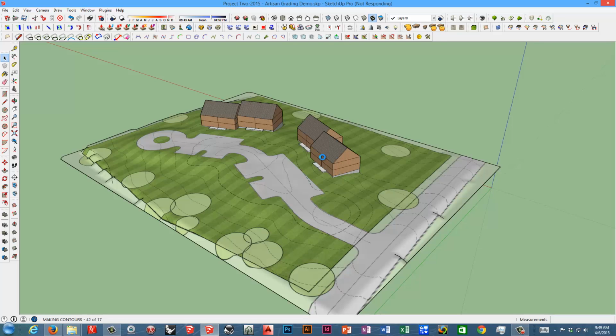So again, I don't know exactly what the slopes are, but if you know what the existing slopes are on there, do a little site analysis before you begin. And you've got the edges of the buildings to kind of tell you if you're dropping 6 or 8 feet, whatever it might be, you can get a pretty good feel for how it's going to work. And then, as I said, once it's done, you can apply the contours, and in a second here, you'll see the 1 foot contours. And because I brought this in with the elevations set from AutoCAD, those contours are at even elevations.